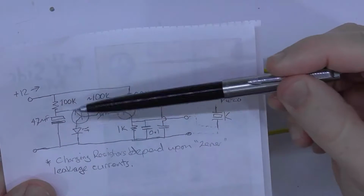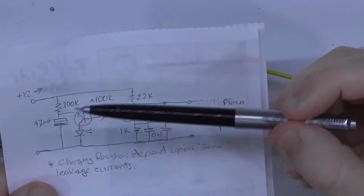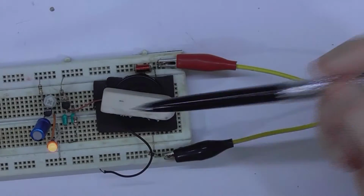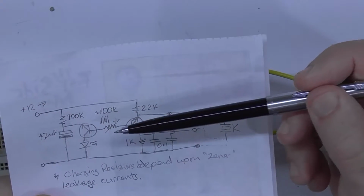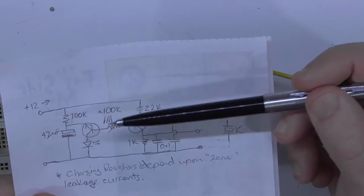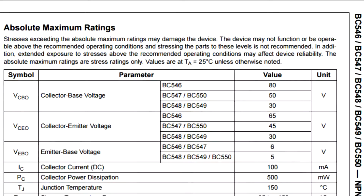The 100 kΩ resistor that I've got here, that I'm trickle charging through, is pretty much on the cusp of operation of these transistors. I'm using BC547s, or in fact, I think on the low frequency one I've got a 546 at the moment. And the reverse breakdown voltage on those, I think they're both 5 or 6 volts. I'll insert the data sheet and have a bit of a squeeze at that.